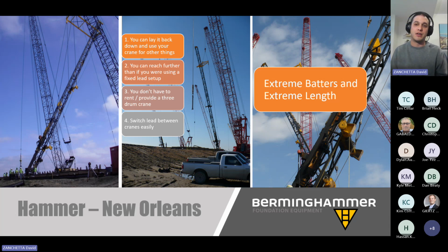The levees in this area are typically composed of very long H-piles driven in on very aggressive batters. The piles are so long and the batters are so aggressive, think batters like 3-to-1, 2-to-1, 1-to-1, that vertical travel leads become impractical to use. Hence, the flying leads are set at a batter using the bridle. So the bridle leads are essentially just flying leads set on an angle.